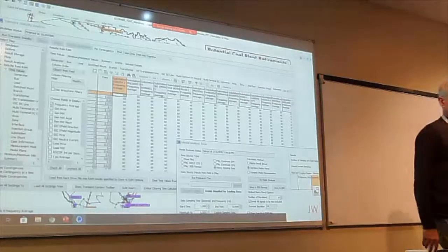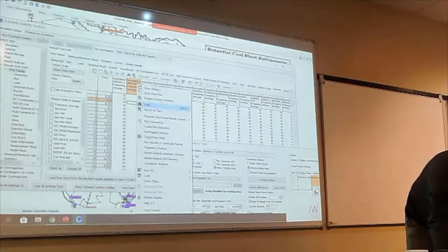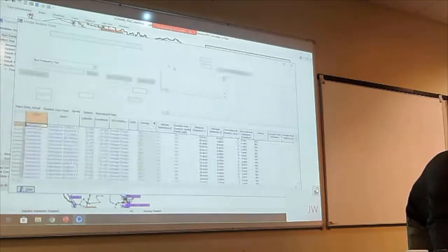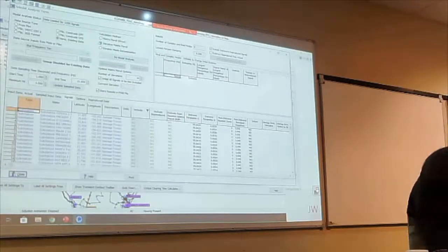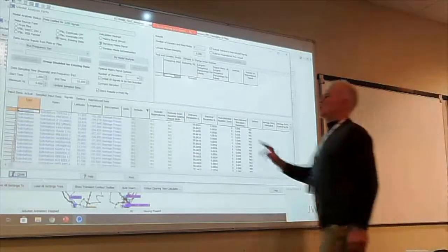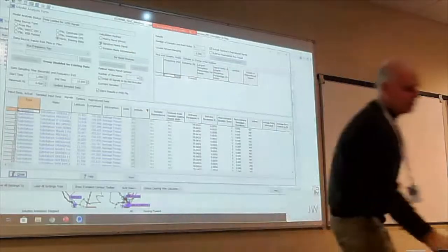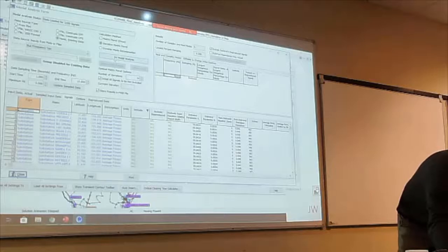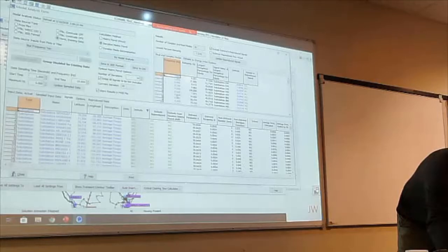All right. And then if you right click on any column, you can do the modal analysis all columns. Okay. And that brings up this page. Then change the option to iterative matrix pencil. All right. Then click do modal analysis. All right. So now I'm mostly caught up. Hopefully you're all the way caught up.